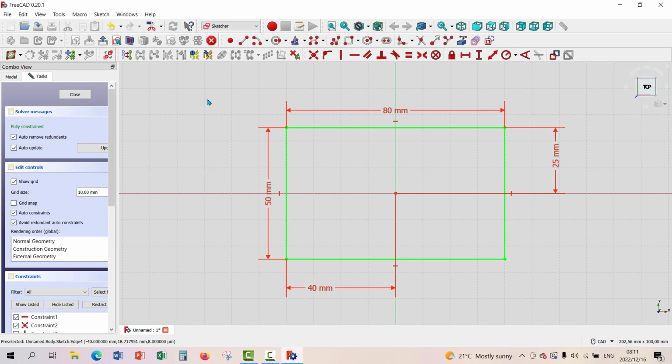And then we are going to start using the polyline again and create a geometry inside here that we can constrain. So let's do this. We go to polyline, and we say, okay, we're going to draw a line from there, say to there, up that way, and then let's use the M key. There we go.